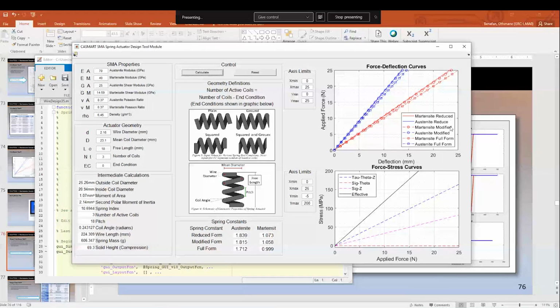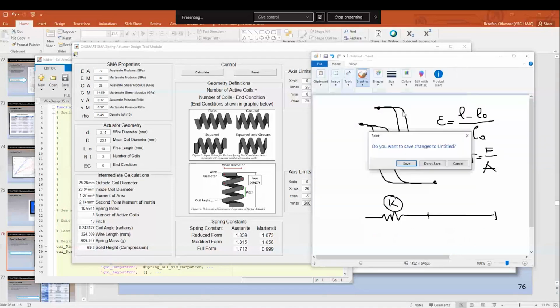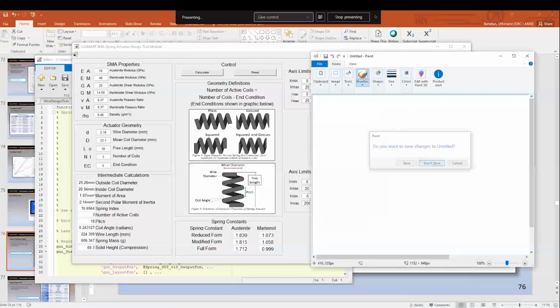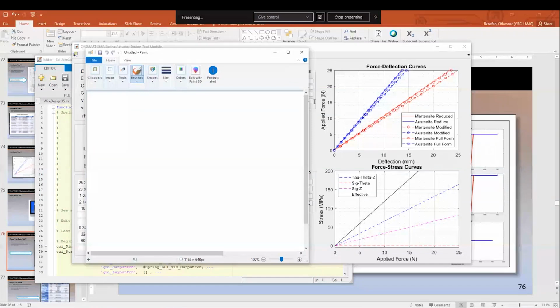And what it really is, it's just the way the springs are calculated. So if you look at stresses in a spring, I'm just going to move this over here. If you look at the stress on a spring, what we're using is the shear stress is equal to some force that you apply to it, times the mean coil diameter. There's some factor that goes in there, divided by pi d cubed, something of that sort. So the shear stress is the highest stress in a helical spring.